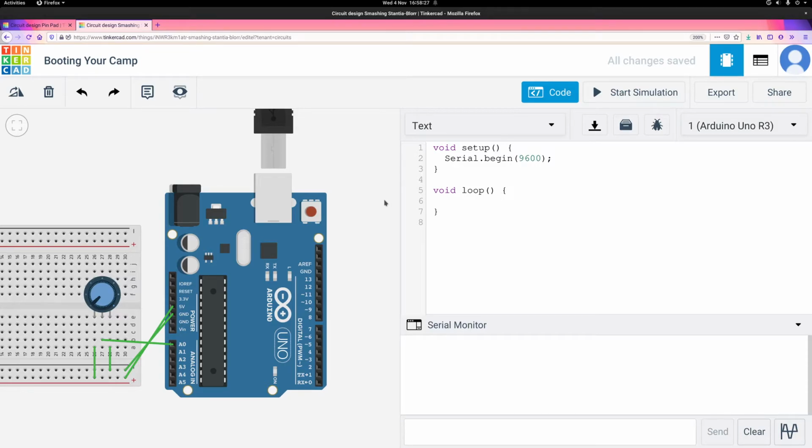And then what we can do inside of our loop is read our analog pin. To read our analog pin, it's very, very simple. Again, which is good. Arduino is good at making it simple. You can just do analogRead, and then you tell it which pin you would like to read. So actually, right, I said earlier that variables were optional here because we only need the variable, like the pin number, in one place.